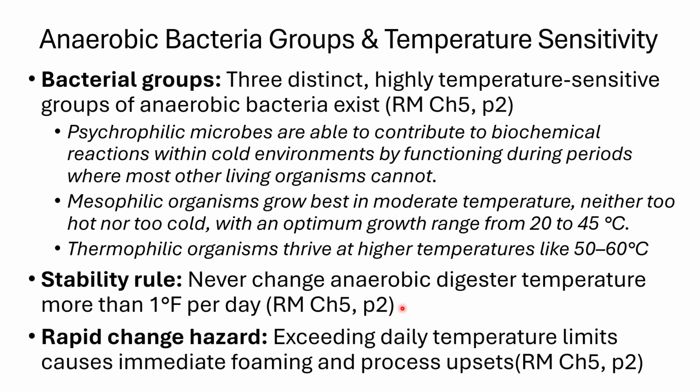Again, for anaerobic digester temperature movement. If you exceed the daily limits that we talked about here, it can cause immediate foaming and process upsets in your anaerobic digester. And foaming is just a visual.